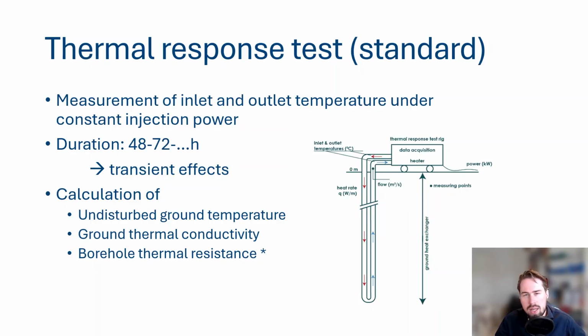And the reason why this test takes so long is that you have transient effects. So if you recall our discussion on the borehole effective thermal resistance and the short-term effects, we said that this was a steady state behavior, that we have transient effects, namely the thermal inertia of the fluid and the ground. So if you can imagine, if you put hot water into this borefield, this heat is not directly transmitted in the ground.